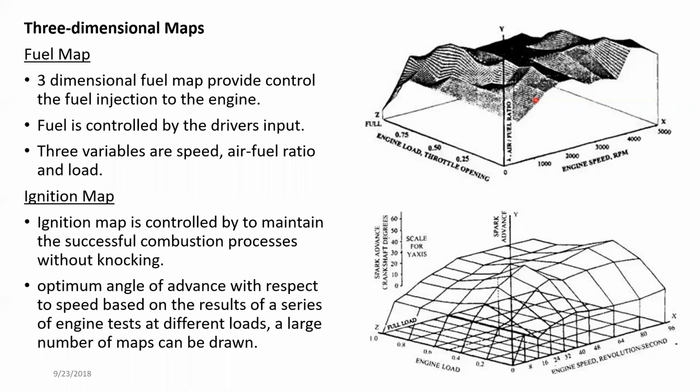Once the fuel is provided to the engine, the lambda sensor provides feedback on whether the engine is doing well with the fuel, meaning whether the combustion process is good or not good. If it is good, no problem, the fuel can be maintained. If it is not good, the engine has to reduce the fuel or change the fuel. For example, if it is a rich mixture, it tries to reduce the amount of fuel. While this is happening, the ignition system checks whether knocking is going on.